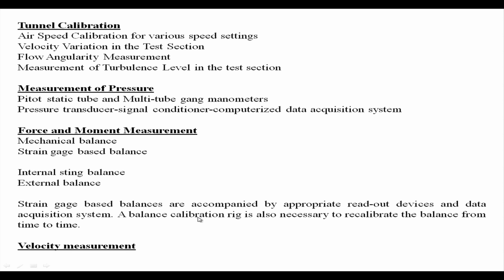It is not only for the balance, but you need to recalibrate them from time to time, whether it is a pressure transducer or a balance. When you initially purchase it, you may be relying on the initial calibration that has been done by the company which supplied the balance. But over a period of time, we know that things tend to drift away. So, your results will no longer remain reliable after a period of time. You will find there are aberrations coming up, things which are unexpected coming up gradually. So, that is the time perhaps that you look at recalibration.